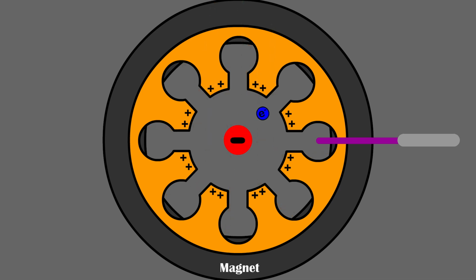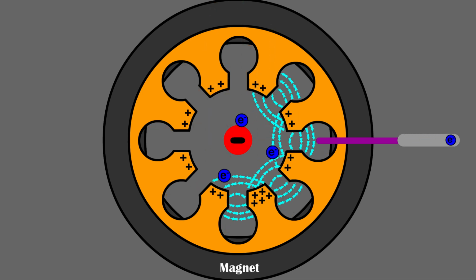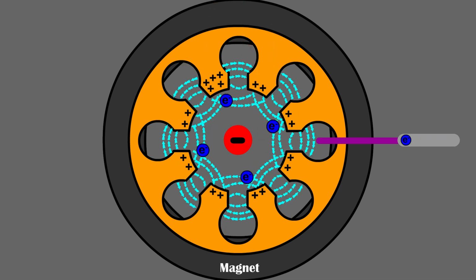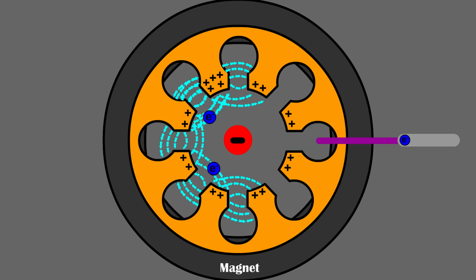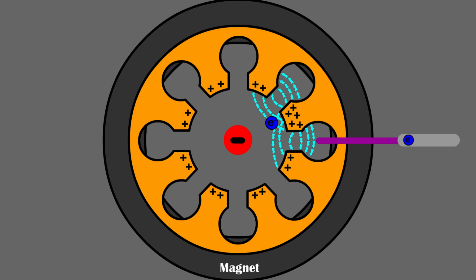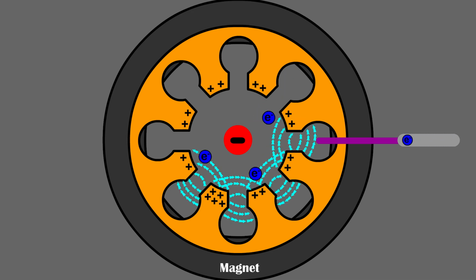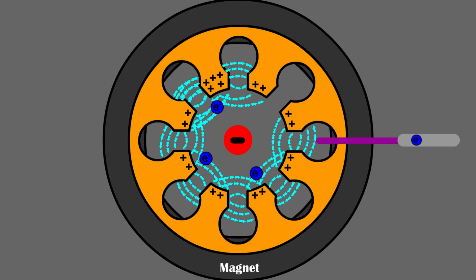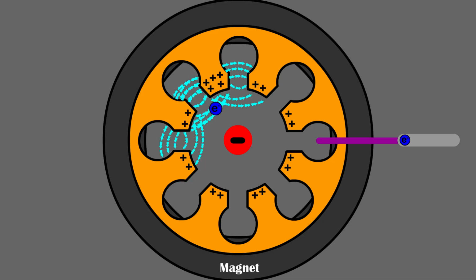Another factor that changes the frequency is the strength of the magnetic field. Increasing the magnetic field strength causes the electrons to move faster, thereby increasing the frequency. However, if the magnetic field is excessively strong, the electrons may return to the filament source instead of reaching the anode, leading to inefficient magnetron operation.